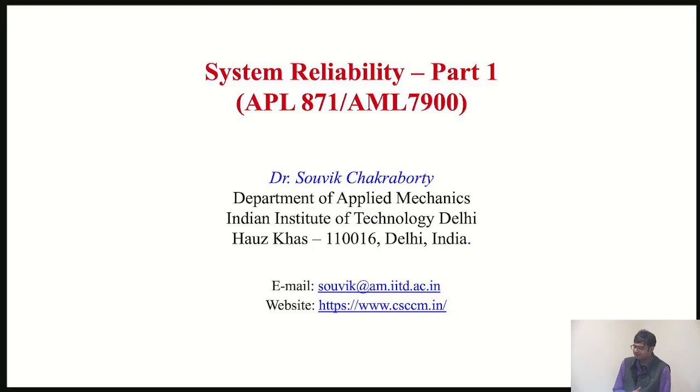reliability analysis methods fall in more or less three categories. The first category was based on Taylor series. There you have the FORM, you have the SORM, and you also have HORM, which is not something we have discussed, not in the syllabus, but that also comes under the same category. So you have the first order reliability method, you have the second order reliability methods, right?